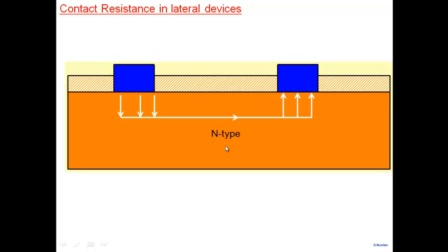And as they flow laterally, they encounter this N-type semiconductor, so they'll face a resistance also. So things are more complicated. Now you can see the carriers are starting from here, then flowing here, starting from here, flowing, and all over. It's a distributed current here. And the drop that takes place through this entire region is my contact resistance.